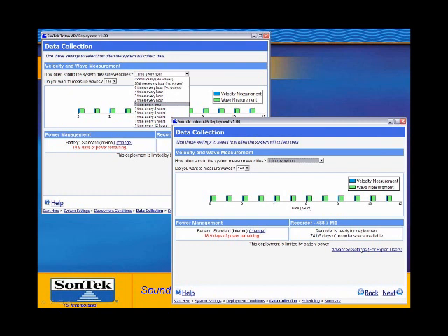Okay, the next question is from Jessica. She's asking, can you deploy the Triton on a mooring? And the answer to that is, it depends. The Triton does have the capability of what we call vector averaging, meaning that it compensates for its own movement. But because we're sampling the data at the rate that we're sampling, the movement of the mooring can't be too fast, for lack of a better term. Really the system that we have for a mooring deployment is called the Argonaut MD, and that one is perfectly capable of handling all mooring situations.